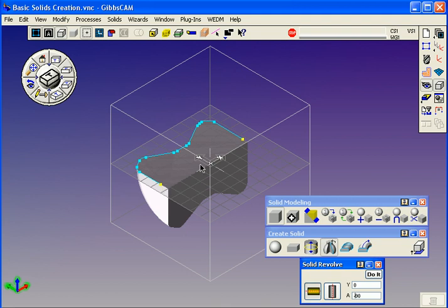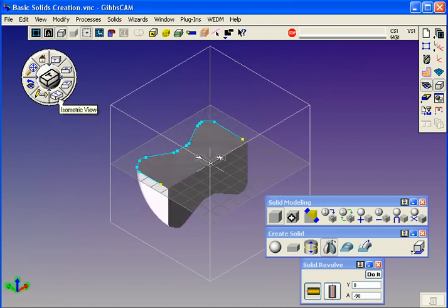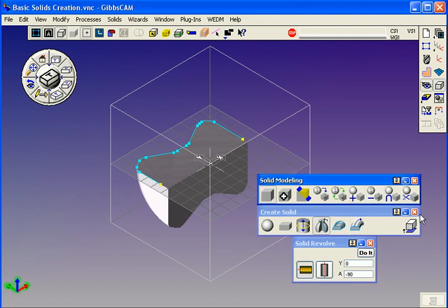As a matter of fact, sometimes you don't want to do it closed. If a geometry section happens to revolve around itself, you'll get an error and it won't let you do that. So it's a good idea not to have these as closed shapes. And you can use this tool to generate many types of revolved solids. Very handy way of taking simple 2D wireframe geometry and converting to full 3D solid models. That's pretty much all you can do with the revolve. We're going to pick up later with the loft, and then we'll do something also about sweep.